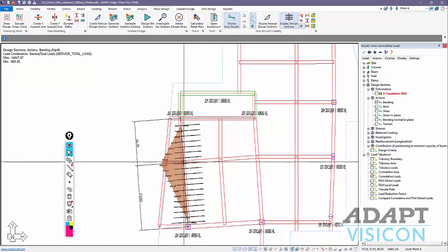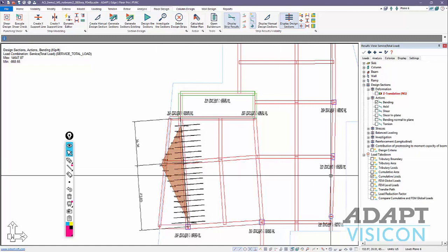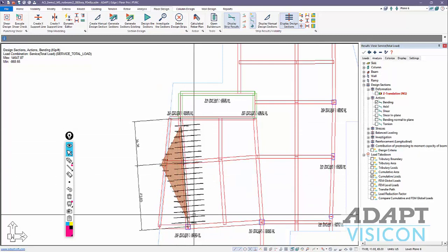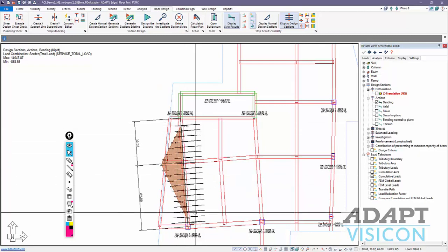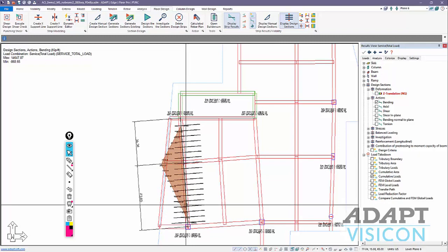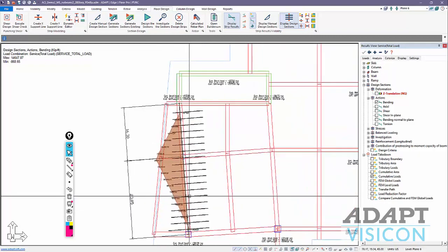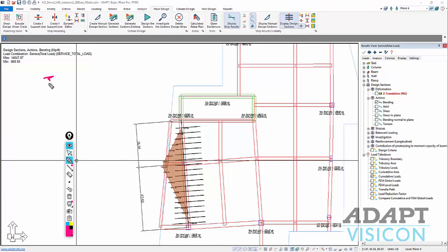In this case, you have more of a one-to-one relationship in terms of the load going to either component, purely based on tributary. So when we run this design, we obviously would get something different in terms of the rebar. We may need to add more post-tensioning. It's really up to the user how they want to approach the design, using load takedown, which is just a method where we can quickly accumulate the loads based on tributary, or using the finite element approach that we ran previously. The third way to do this, I'll call it an indirect approach, is using the FEM reactions.